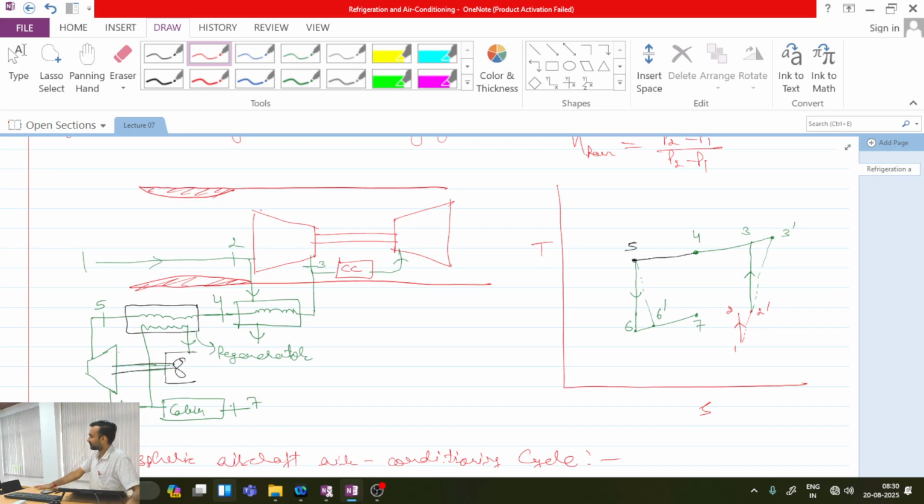Is this one clear? So, regeneration cycle with evaporative cooling: the only difference is that in this second regenerative type heat exchanger, whatever cooling medium I am considering is some externally low pressure or low boiling temperature cooling liquid. Okay, so if its boiling temperature is low, whenever it exchanges heat, it will try to evaporate. And because it is in liquid phase, its conductivity will be significant, so the performance of the heat transfer process will be effective.